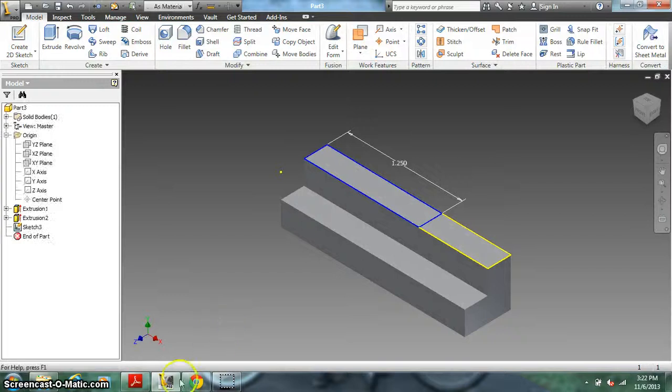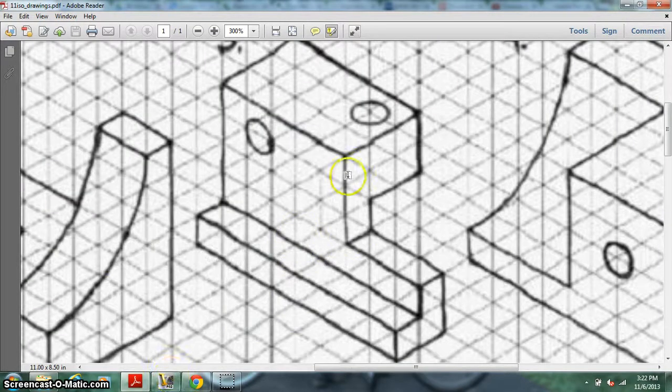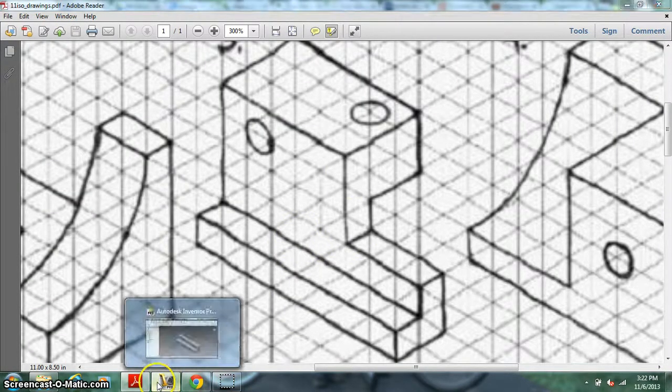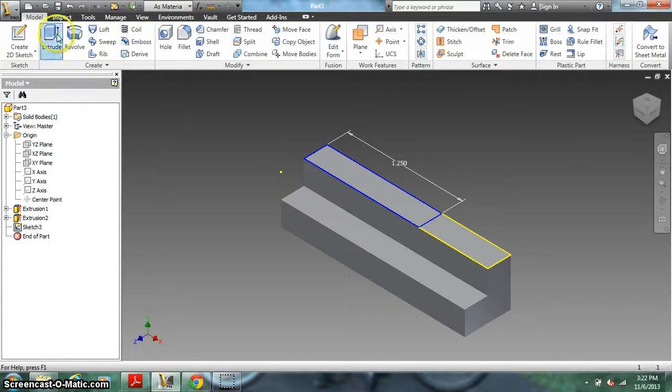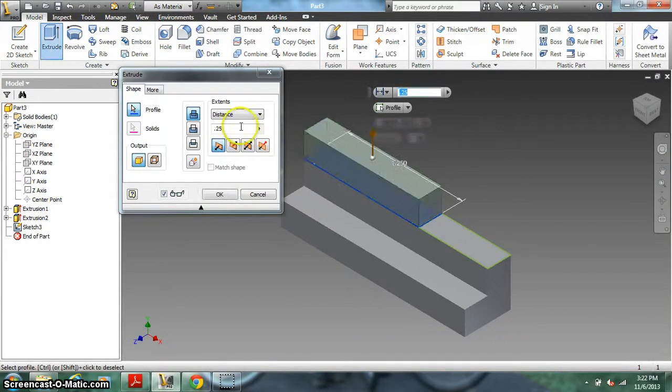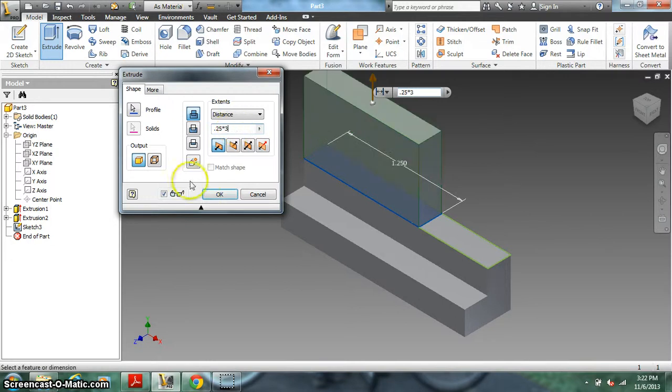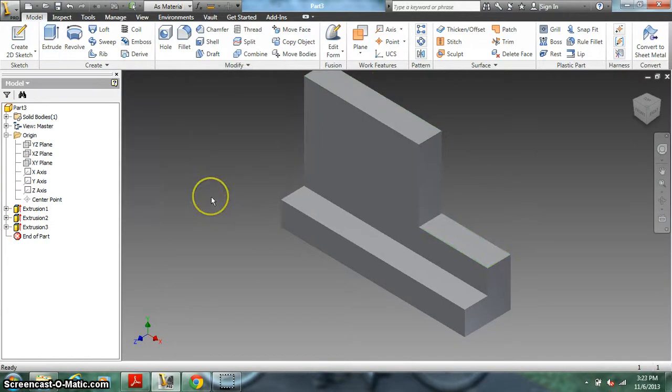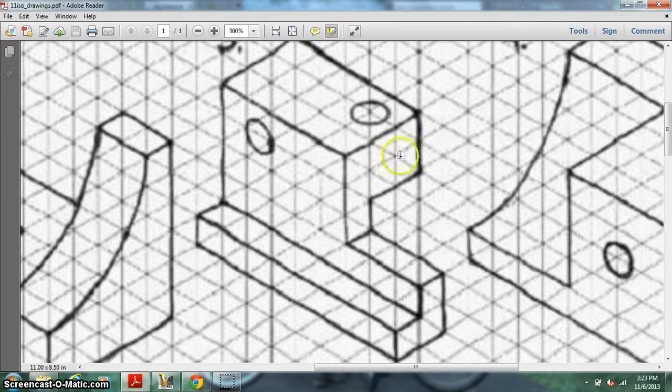Finish my sketch. Now let's check how high it goes. 3 blocks high. Extrude that surface, 0.25 times 3. Alright, now I've got that wall. Here's where it gets a little trickier. We have to kind of extrude out this direction, 2 additional blocks, 1 higher.